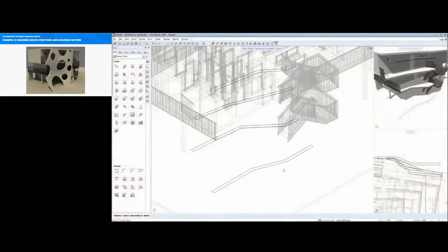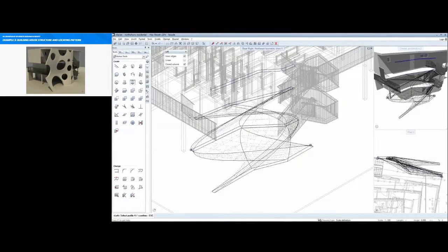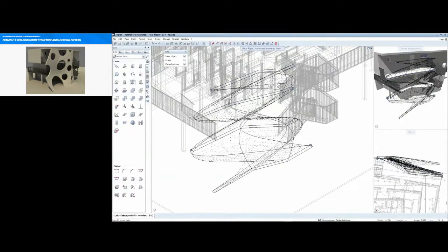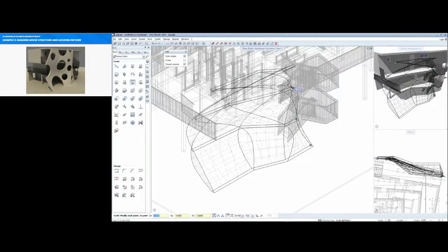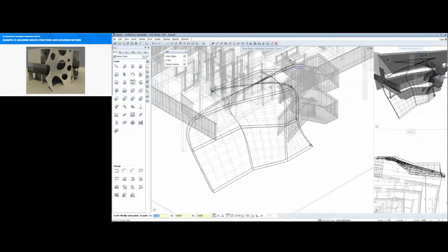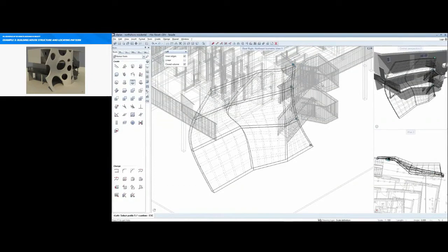The Lofts tool in Allplan allows you to model objects from different cross-sections. An in-part organically shaped surface is modeled from cross-sections in order to create a facade. You can select individual cross-sections with the Lofts tool and generate an object from these. You can also adjust the starting points of the respective cross-sections subsequent to this, depending on the alignment of the cross-section. The Lofts solid then reacts to the adjustment of the starting points on the particular cross-section.